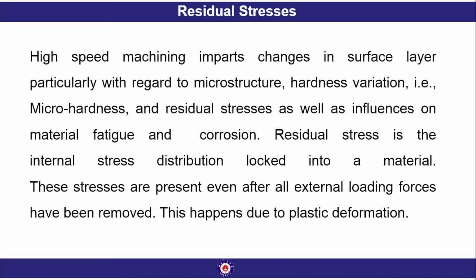Another important property of surface integrity is residual stress. High speed machining imparts changes in the surface layer, particularly with regard to microstructure, hardness variation, that is micro hardness, and residual stresses, as well as influences on the material fatigue and corrosion. Residual stress is the internal stress distribution locked into a material. These stresses are present even after all external loading forces have been removed. This happens due to plastic deformation of the materials.